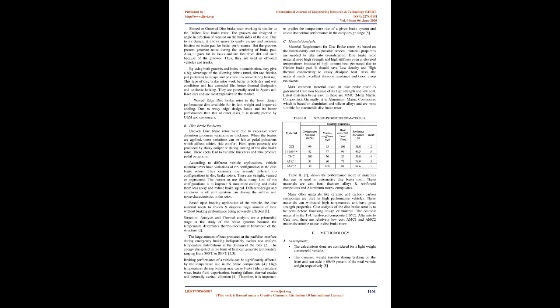Vented disc brake rotors are needed for dissipating excess heat through vanes or spokes present in between two discs. Due to the large contact surface with fluid air, the heat can easily dissipate by radiation via the vanes or spokes. There is a slight increase in disc weight, but with more durability and effective cooling of the disc for better performance. These vanes or spokes help in better ventilation and thus prevent cracking of the disc.